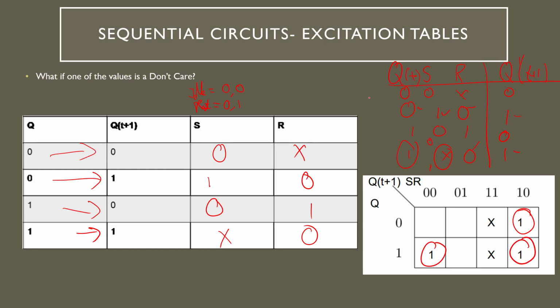But here's something interesting. We know that for an SR latch, 1, 1 is forbidden, not allowed. That means that we don't care what happens at 1, 1. So we put down two x's. So now not only does the output have don't cares, the input has don't cares as well. Input don't cares are reflected by a double entry on the truth table, output don't cares are still reflected by an x. Now I can make my groups, this group and this group. And I'm going to erase that truth table up there real quick.